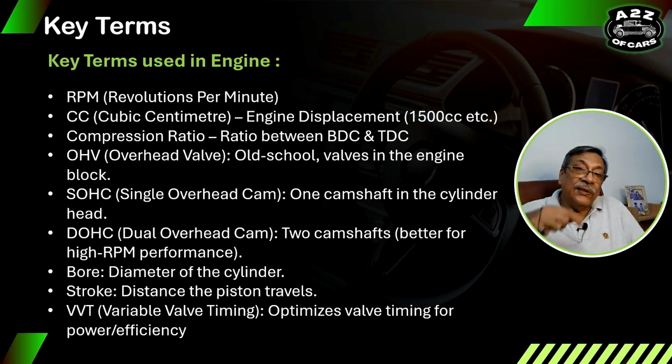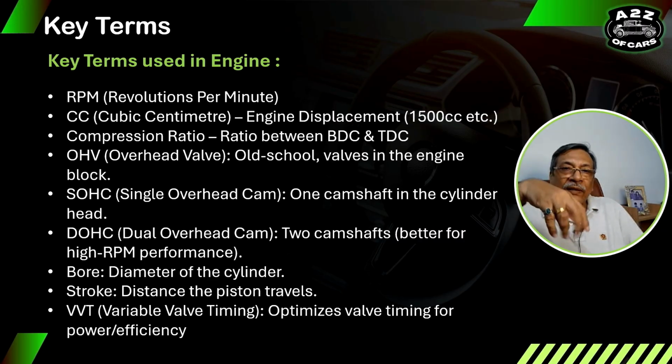Then the bore. You have seen that cylinder, that round hole inside, that is called the bore. That is the diameter of the cylinder. Then stroke, the distance the piston travels, TDC to BDC, that is one stroke.